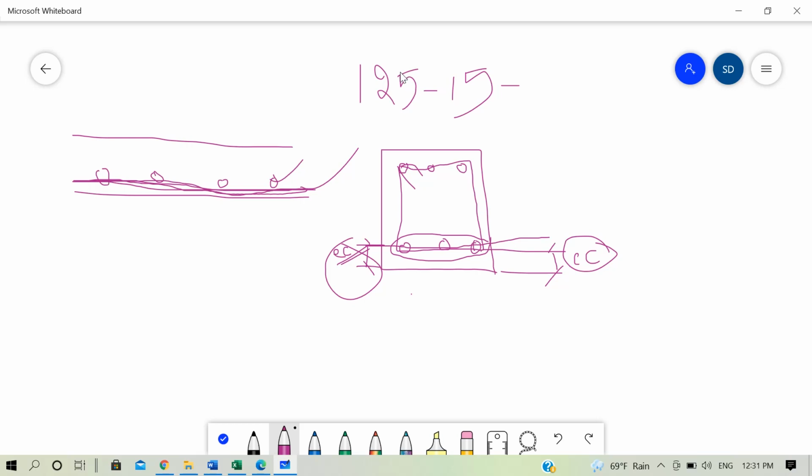So to find the effective depth for the slab in the shorter direction, we have to take the dimension from the centroid of this bottom reinforcement layer. This bottom reinforcement we have also supposed to be 8 mm. Now we subtract: total thickness of slab minus clear cover minus 8 by 2.